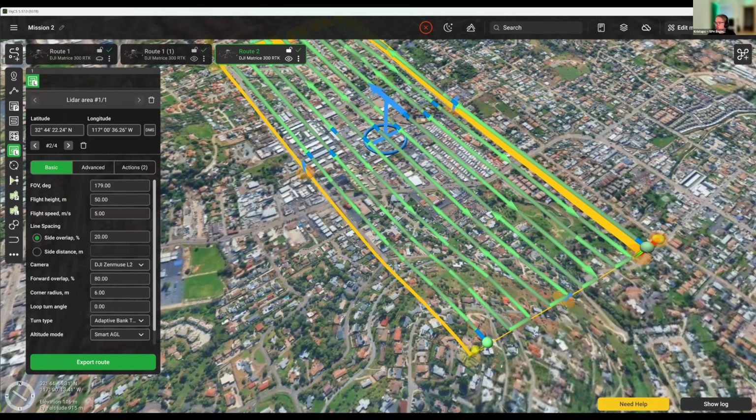So I suppose if you're using a LiDAR with 360 degrees field of view, you can simply set this to 179. But I would say that even using the standard 70-degree angle is a decent approach, because you will still have more than sufficient overlap, since of course your LiDAR's field of view angle is even higher. So that's about that.